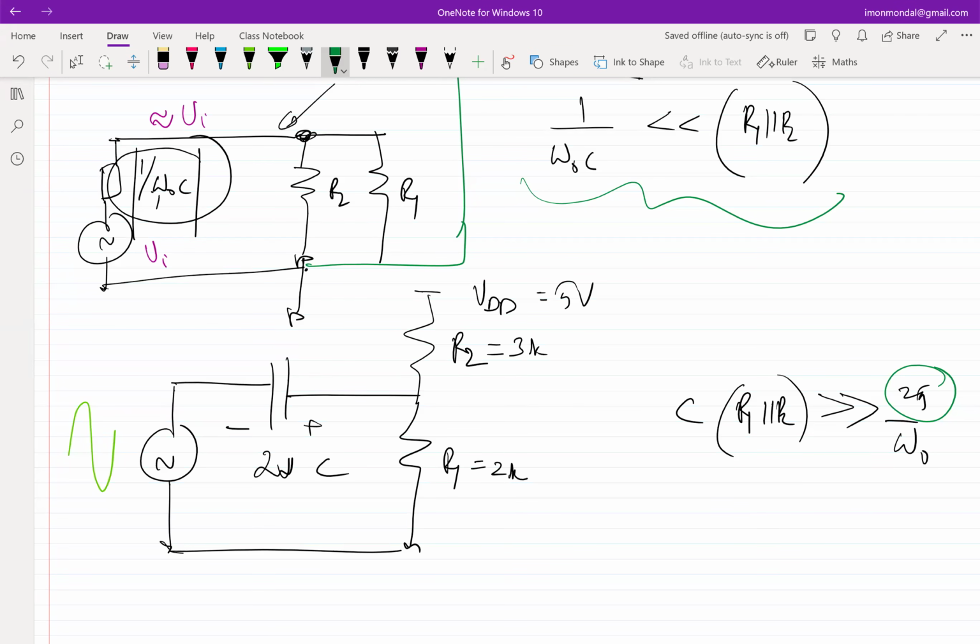The period that we are talking about is one cycle of your sinusoid, and as long as the capacitor is able to hold its DC value without much change, because it is going to change, across the full cycle of an input, it behaves like a short circuit, right?